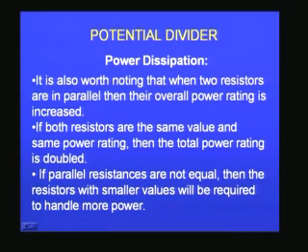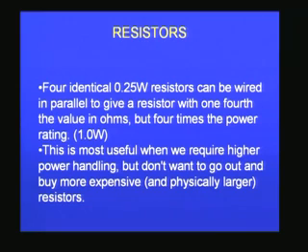We should always use resistors which are not too small and not too large, but something in between, maybe about 1000 to 2000 ohms will be a reasonable value of resistors to be used in parallel or series combination for obtaining potential dividers.